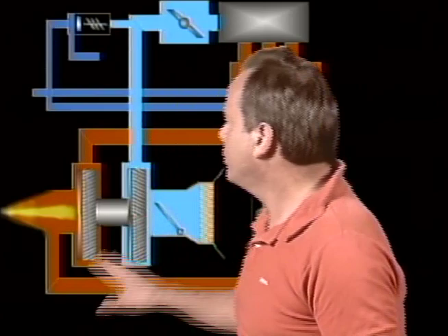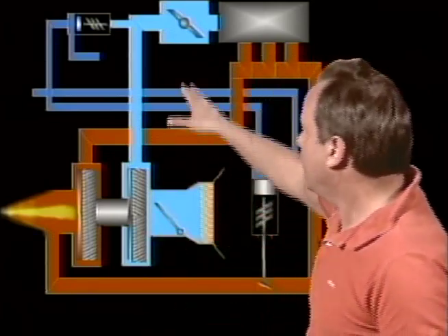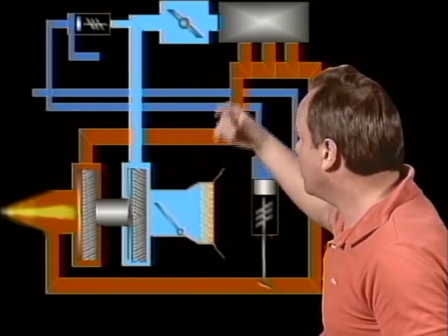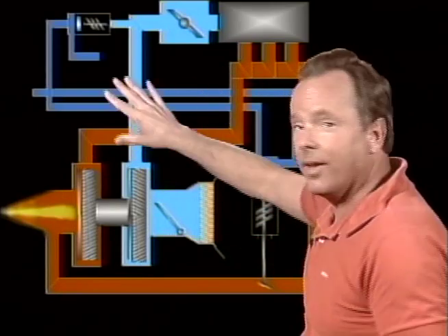All right, now what is the purpose of a rate of change controller? Well, if you have a turbo-normalized system, you also have a rate of change controller, and what it does is controls the rate at which the turbocharger discharge pressure will increase. It just will not allow the turbocharger to increase or decrease rapidly. That's the rate of change controller. It just smooths things out. That's actually part of the density controller.